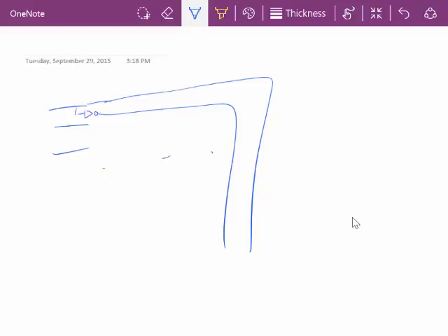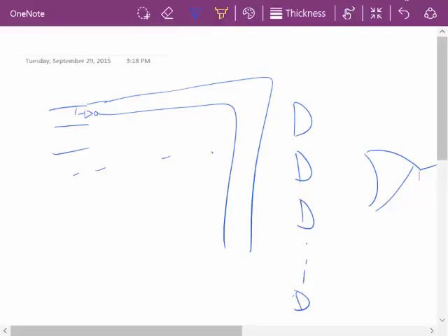We have a bunch of AND gates, however many we have, and then they feed into one OR gate right there. That allows us to do a sum of products term from any truth table. And we don't have to have individual chips. All we have to have is the truth table, and the software will then take the truth table and develop the circuit, setting the configuration for us. And that's the simplest form of PLD.